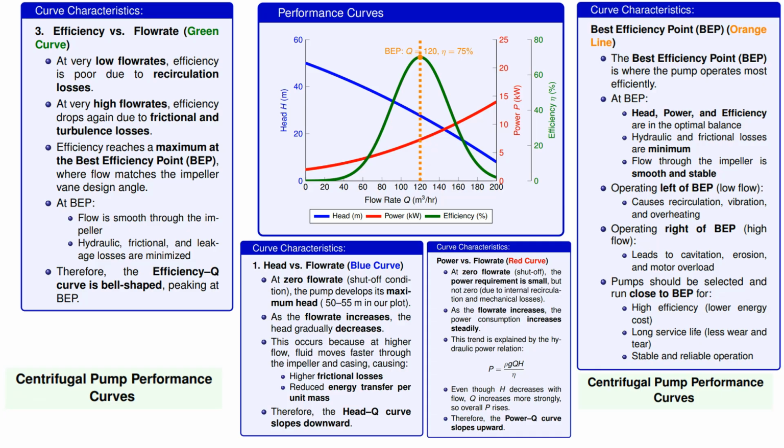And that is your complete guide to the centrifugal pump performance curve. Remember, the blue head curve drops, the red power curve rises, and the green efficiency curve peaks at BEP. Understanding this relationship is the key to proper pump engineering.